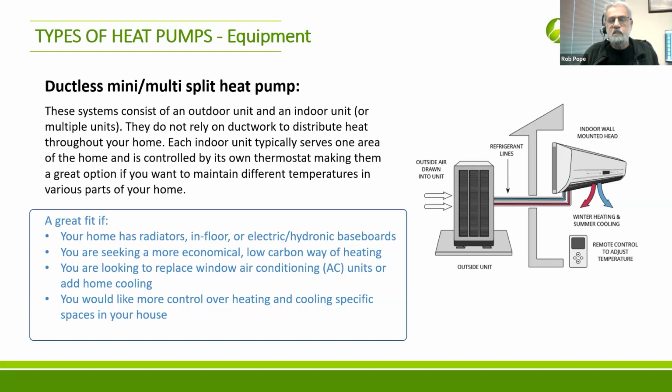It can only do what it sees. Now it can move down a hallway if it's not too far, but it can't make right turns and go through doors to the next room over. That next room over, maybe it's a bedroom, needs its own. So it can add up to take care of each of the rooms. So you've got to be careful about that. That's a lot of moving parts and cost and refrigerant lines, condensate lines, wiring, and so on to put many cassettes in the house.